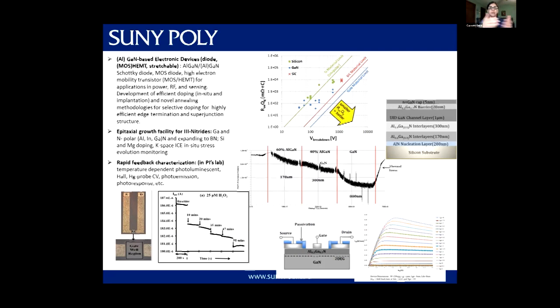Obviously, most of what we currently have in the market are based on silicon MOSFETs. And as the voltage requirement goes higher, silicon cannot really handle it anymore just because of its small band gap. It creates very high heat in those types of power applications. There's an equation that they have not included here, that the power handling of a switch goes based on its band gap. That's a very important factor because it's the electric field it can handle.